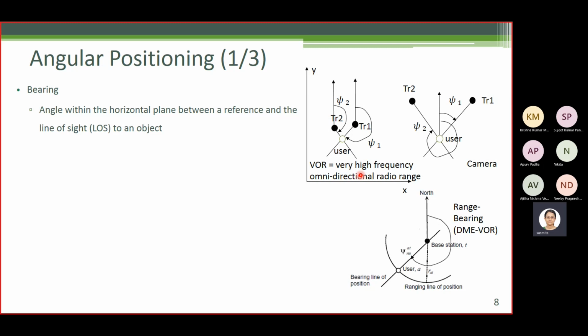For military aircraft, it is still there because by suitable design they improve the accuracy. Basically, they use both DME and VOR, a system which has both DME and VOR, and they name it differently. It's called TACAN. TACAN stands for Tactical Area Navigation. So they actually use DME as well as VOR. They have a different, much more accurate design, but it is equivalent to DME plus VOR.